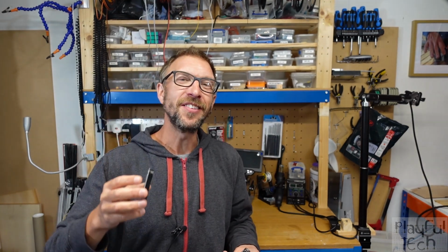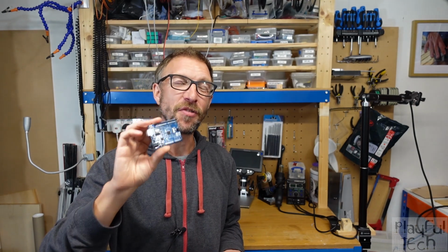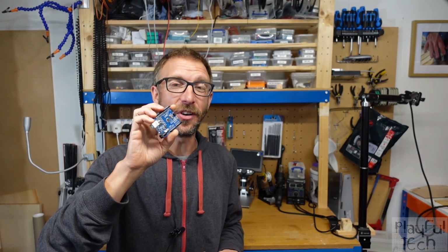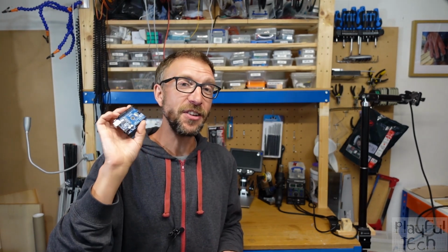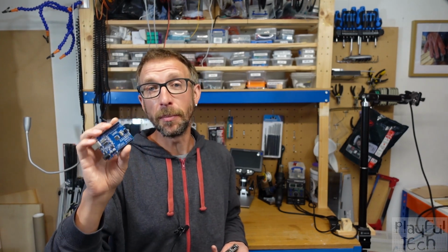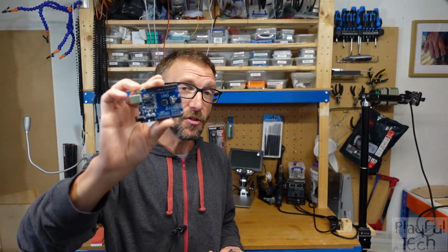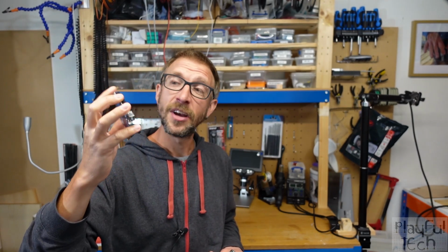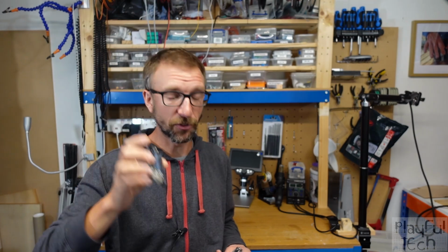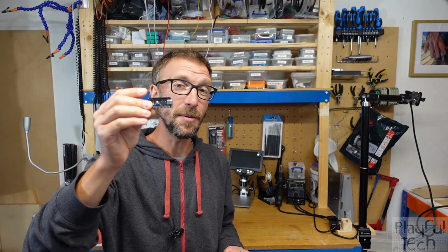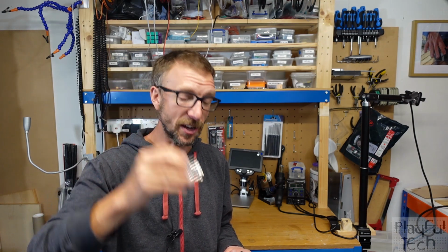Okay, so GPIO pins are essential to making your microprocessor being able to interact with things. Every time you want to connect a sensor or trigger an output, you're going to need at least one available pin. But there's only a limited number of GPIO pins available, and different microprocessor boards have different numbers of them. So an Arduino Uno has 20 GPIO pins, of which 6 can read analog inputs and 6 can generate analog outputs. A Nano is the same, other than the fact it actually has 2 more analog input pins that can be directed to the onboard ADC.